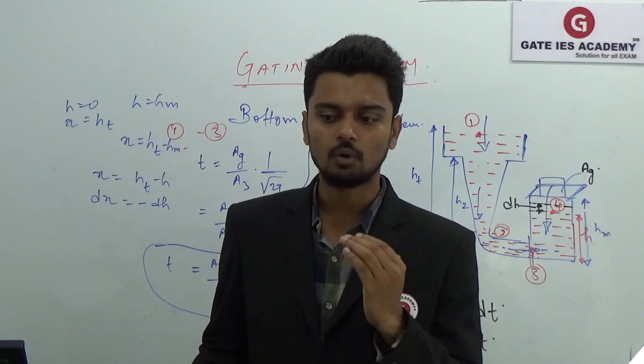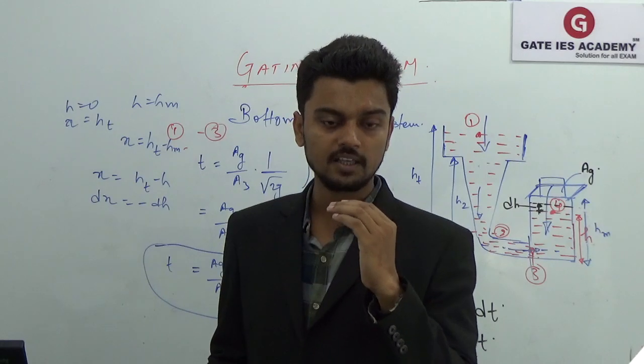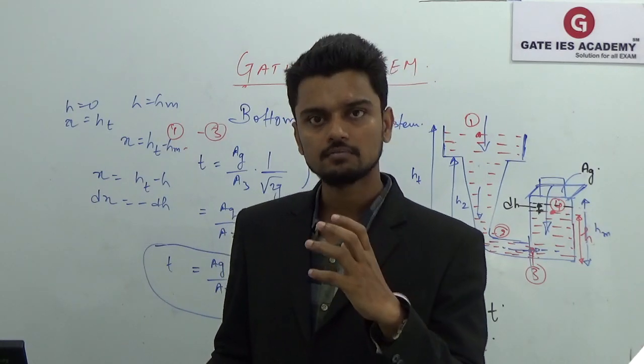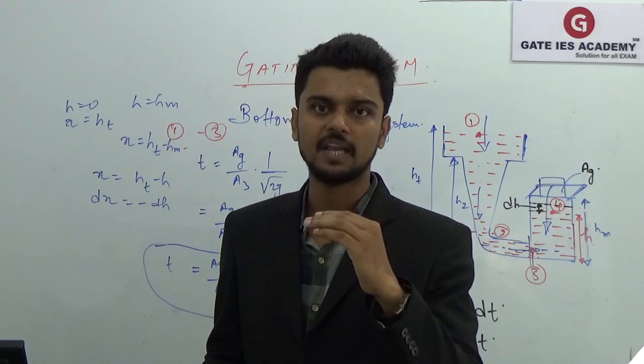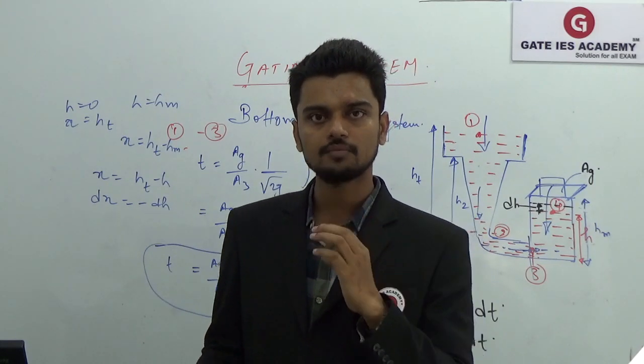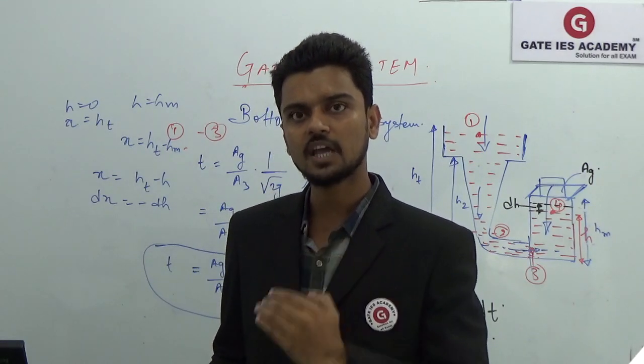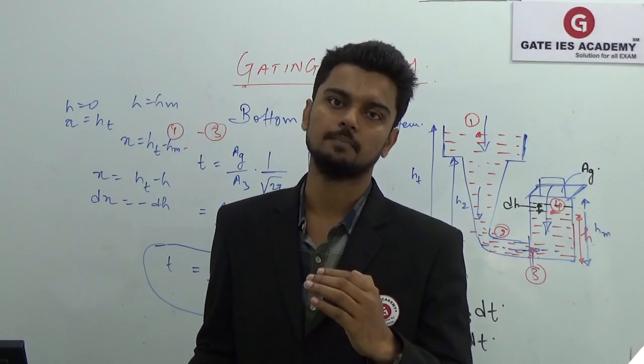If you are keeping that in-gate at the parting plane, half of the cavity will be filled by the bottom gating system and half of the cavity by the top gating system.